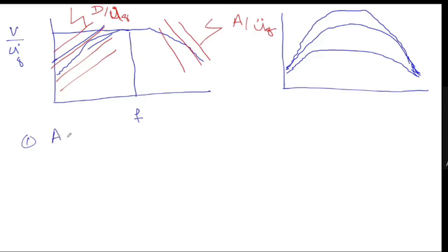the pseudo acceleration, or the acceleration, approaches the ground acceleration, which is true. When the time period is very, very low, the acceleration acting on a structure is exactly equal to the ground acceleration. Okay, and if it is a very long time period or a very small frequency, the displacement demand on the single degree of freedom system becomes equal to the ground displacement.